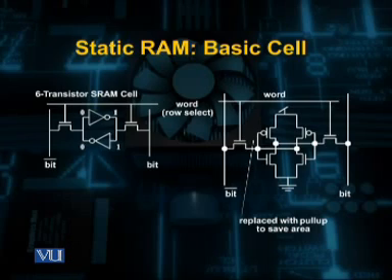Here, please remember that these are very tiny transistors, so we cannot rely on them to drive these long bit lines effectively during read. Also, the pull-down devices are usually much stronger than the pull-up devices, so the first thing we need to do on read is to charge these 2 bit lines to a high value.